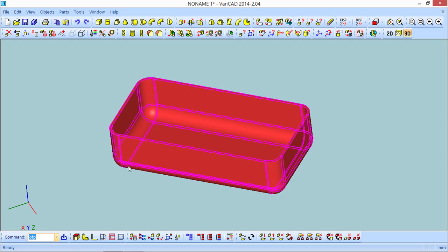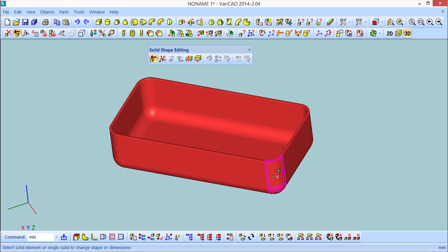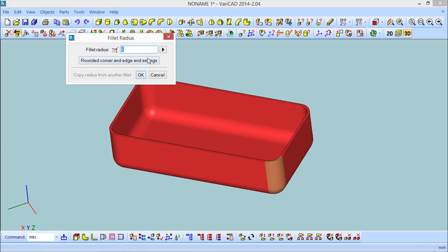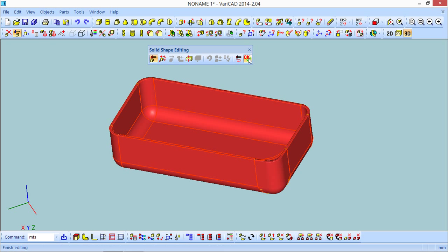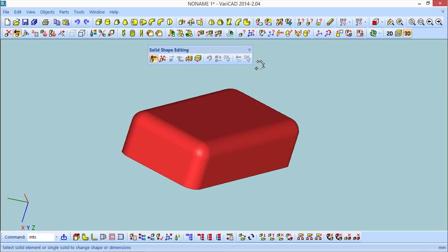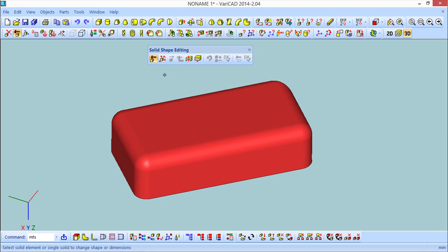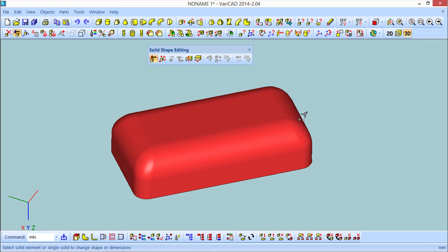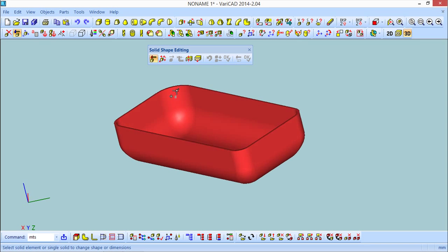I can edit also this kind of solid, and for example, if I do the edition, I can edit this in several ways. First, I can go to one fillet or all fillets and say, edit this, I don't want this, I want, for example, 10, and rebuild this like this. Okay, this is one possibility. I could go to the other. You see that I can click on these ones and do the 10 also. If it is possible, it will do it. Okay, you see that I have this possibility.